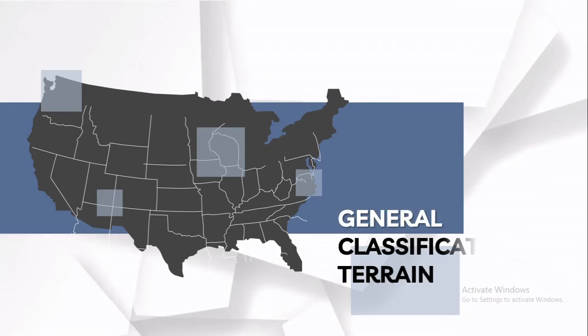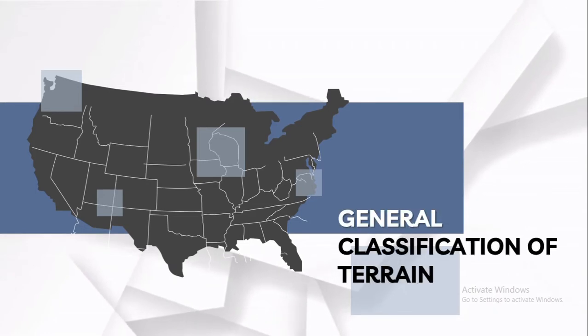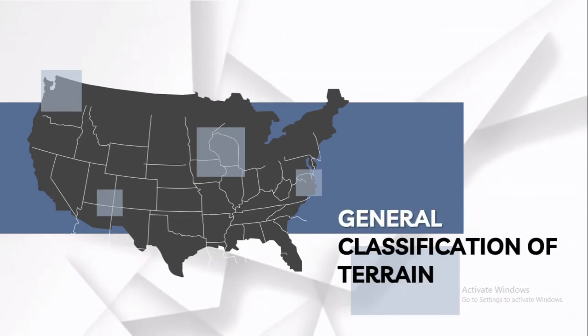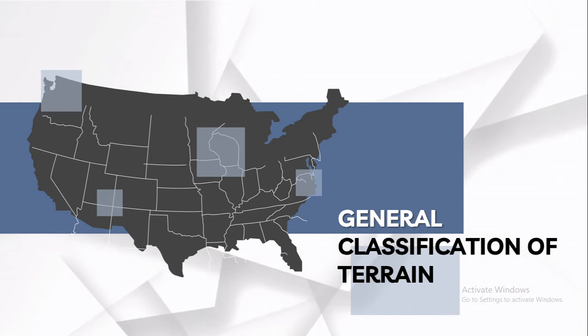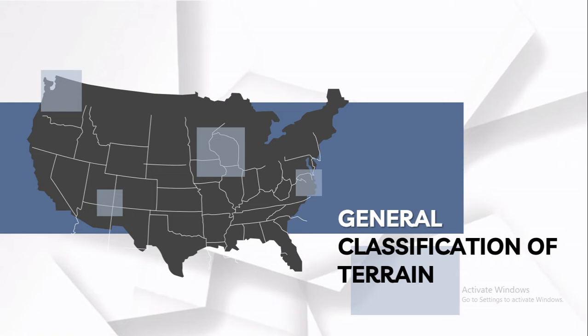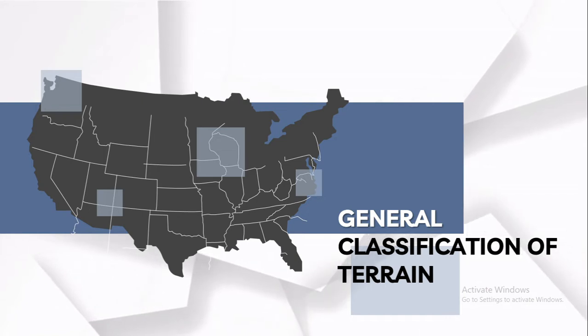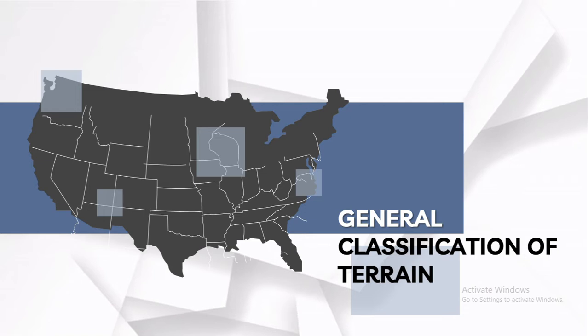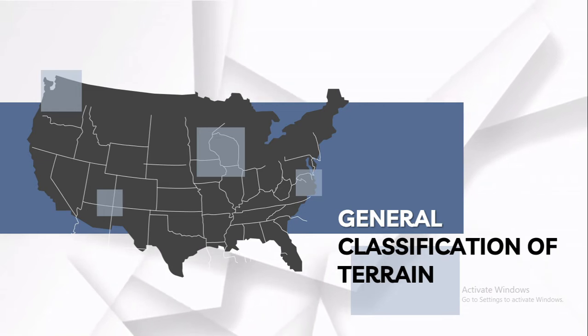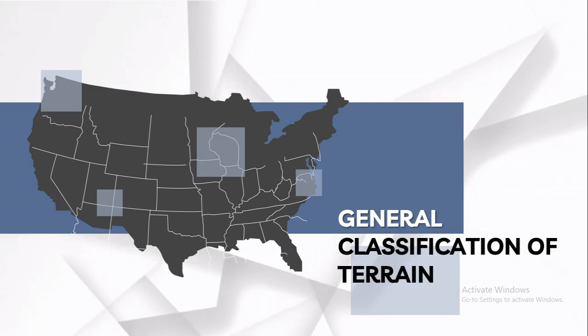The topography of the land traversed has an influence in the alignment of roads and streets. Topography does affect horizontal alignment, but it is more evident in the effect on vertical alignment. To characterize the variations, engineers generally separate topography into three classifications according to terrain. As the terrain and the gradient increases, the construction cost will increase for a specific design speed.